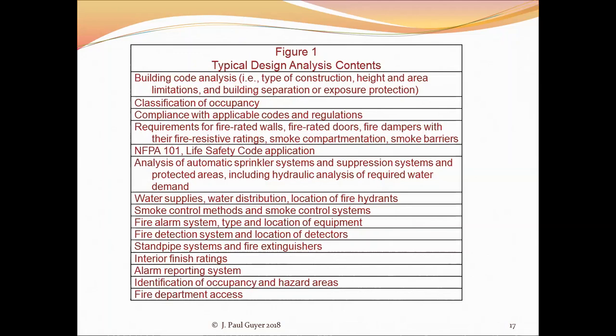If these nearby buildings are very close to your building or right up against your building in an urban environment, then those buildings are threatened by the fire in your building, and you have to do certain things to protect those other buildings, like the fire resistive construction of the separation wall between your building and the building next door, continuing the exterior walls vertically above the roof for a certain distance, 4 feet, 6 feet, something like that, to prevent, in the event of a fire breaking out of the roof, burning debris being blown over onto adjacent buildings.